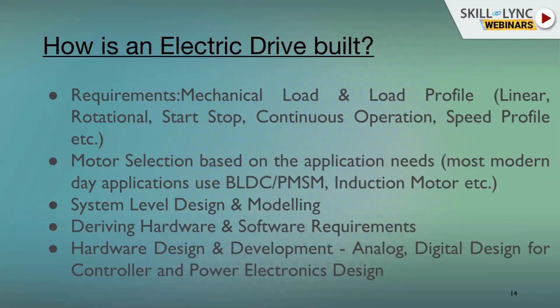Once we have clarity on the requirement, comes the selection of the motor based on the application requirements. It is typically driven by what sort of torque and speed characteristics we require, and what sort of load it is handling. Nowadays, we typically tend to use BLDC motors, permanent magnet synchronous motors, and induction motors. So the motor selection also has to go hand in hand while the drive is being built.